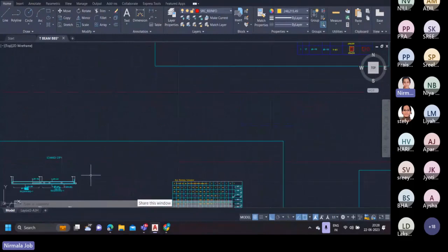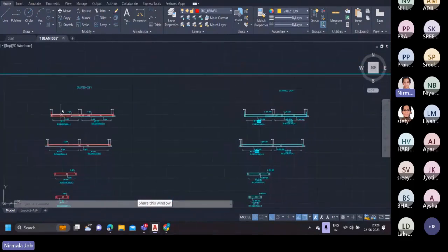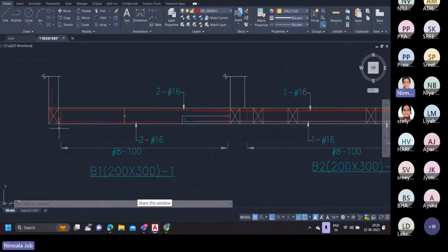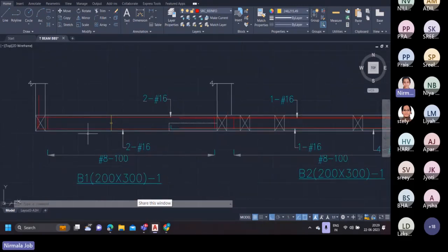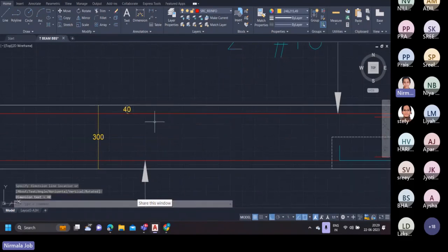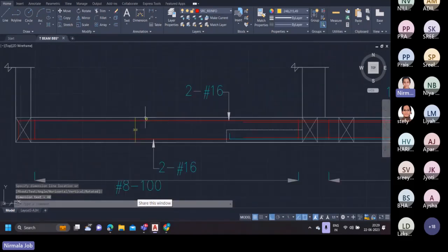Once the drafting part is over, the next step is to denote the rebars. Since the T-beam is actually resting over a PCC layer, these columns should not pass below the T-beam, and should pass only above the T-beam. Hence, we should not draw the columns below the T-beam. After that, we can draw the rebars by providing a cover of 40 mm, like we already discussed earlier. That is, since this structure is in contact with the ground, we'll be providing an increased cover, that is 40 mm.